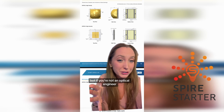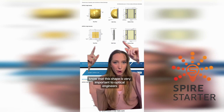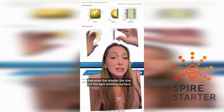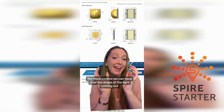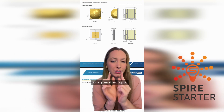But if you're not an optical engineer, but you're trying to pick out a source before you've spoken to one, know that this shape is very important to optical engineers, because the smaller the size of the light emitting surface, the easier it is to control that beam. The more control we can have over the shape of the light coming out for a given size of optic.